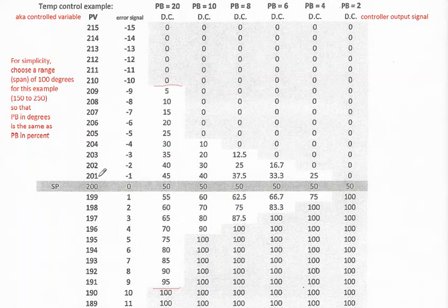And that is a look at gain. The fact that a 1 degree change causes a 5% change in the output signal, that's more of the perspective of gain. And of course, proportional band has this perspective. It's how wide are we in terms of encompassing the 0 to 100%. Proportional band and gain are inverses of each other. So maybe we'll work that out too on paper at some point mathematically, but here we're trying to do it sort of visually.